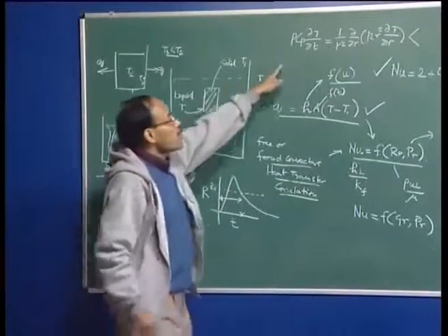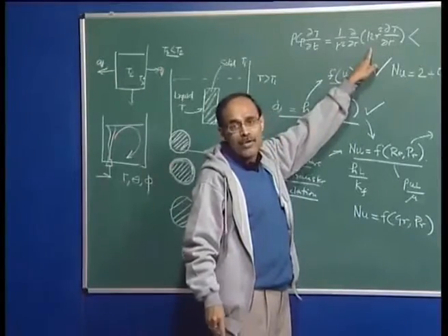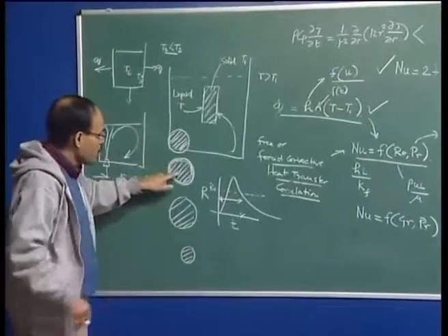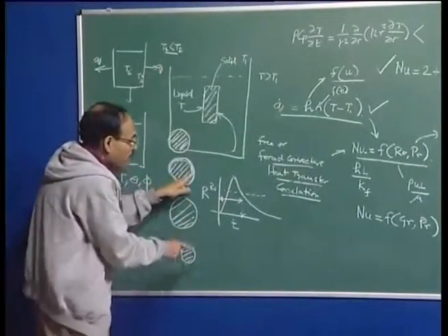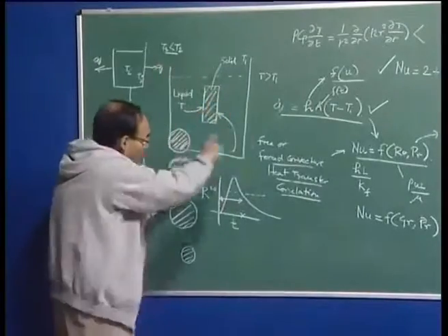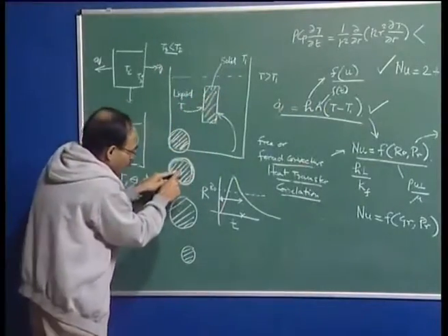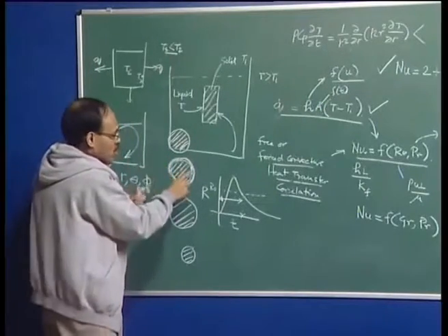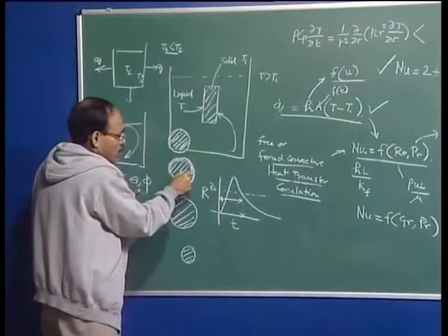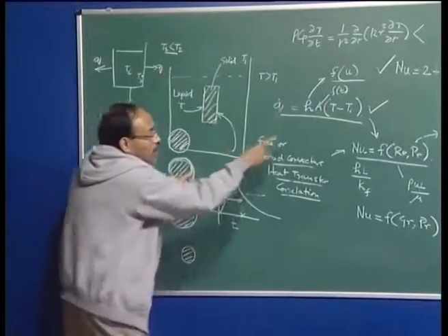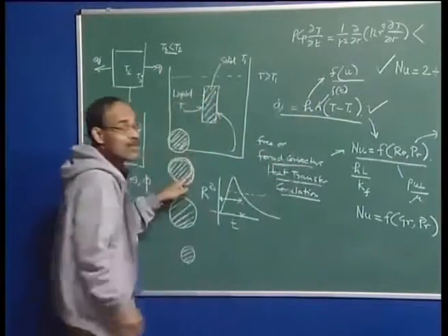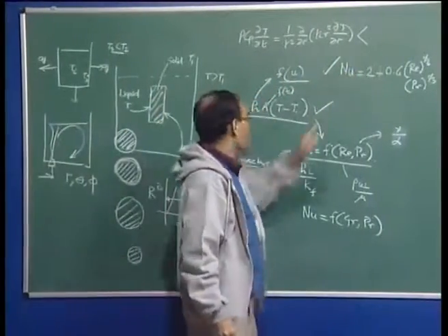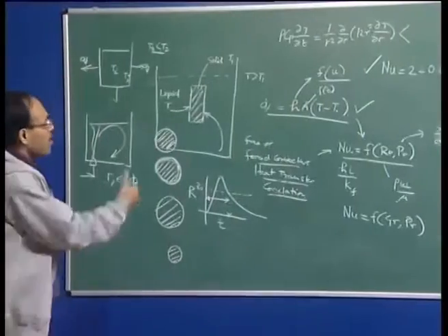Note that in the first equation no information is there on the fluid flow itself. How does the fluid flow part get into the process mathematically? It is because of the flow of heat at the surface, where I require boundary conditions. So through the boundary conditions to that equation, for example, at r is equal to r1, which at a particular instant is the radius of the vessel, I can say the rate at which heat is flowing can be given in terms of the heat transfer coefficient, which is the convective heat transfer coefficient. So through the boundary condition I will be able to incorporate the effect of fluid flow.